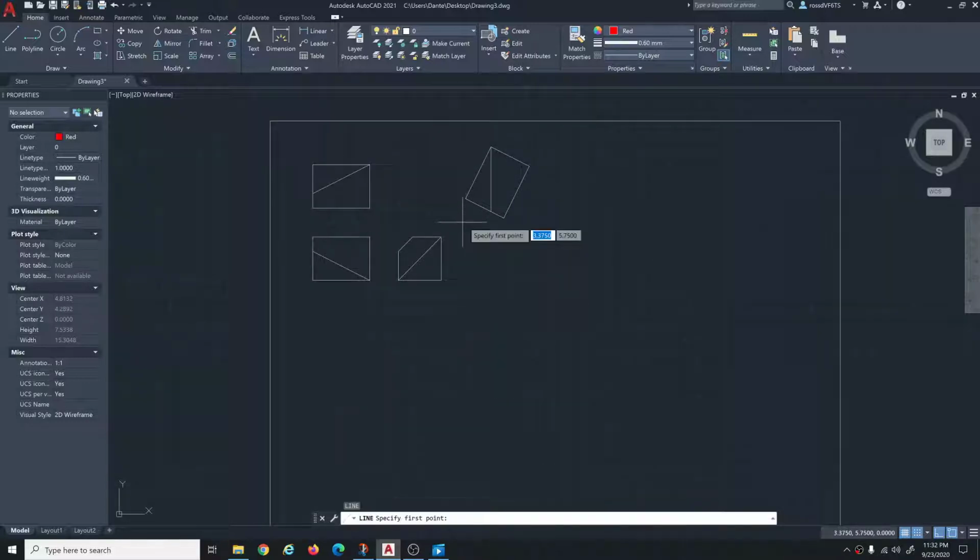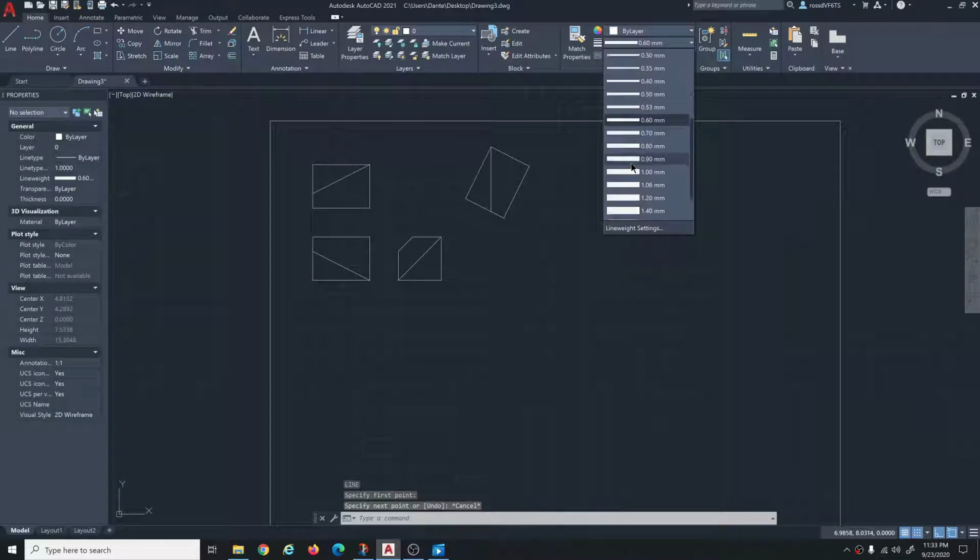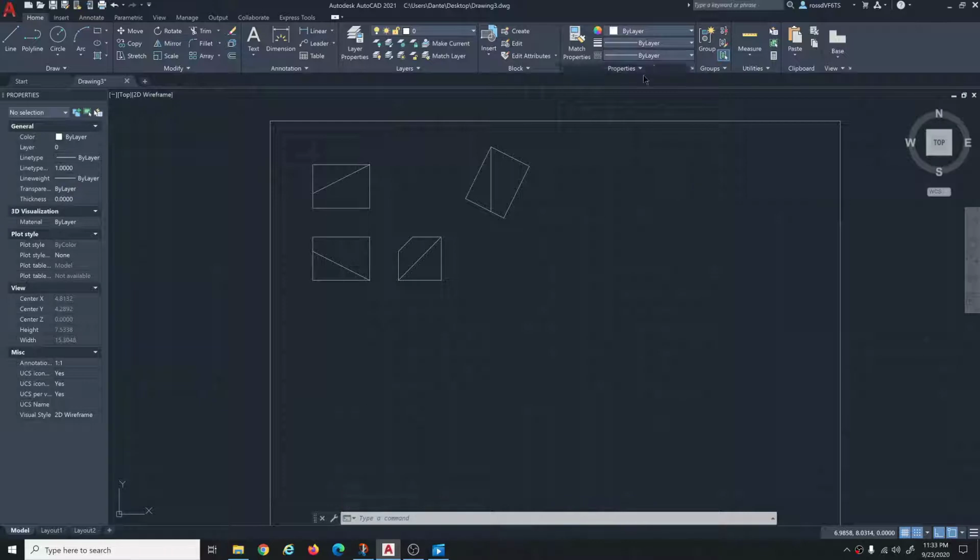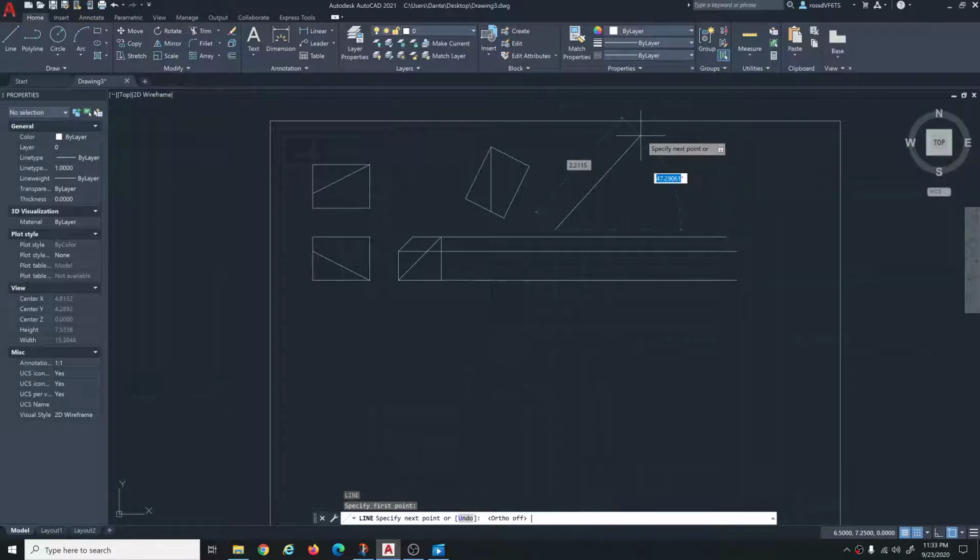Now generate some projection lines. Come off of all of, whoops, let me switch to hairline lines here. So take all of these points, and I'm just leaving ortho on so I can draw these straight out. So get all of these. There's only 3 lines that we need to project. Okay, then draw a 45-degree line about like that, and then project.